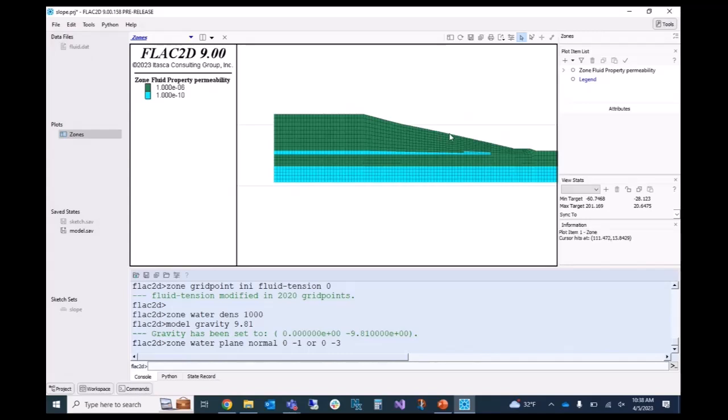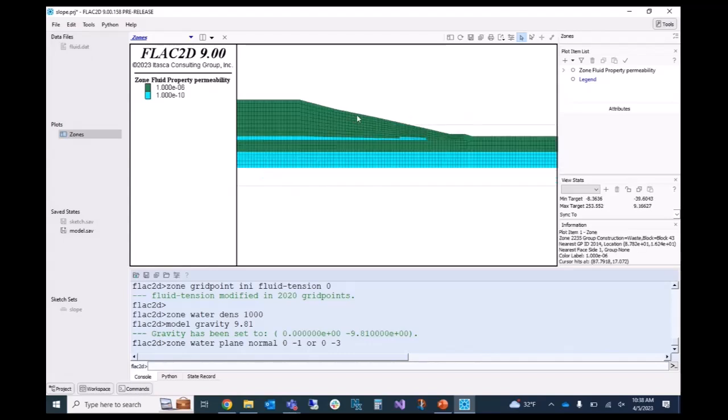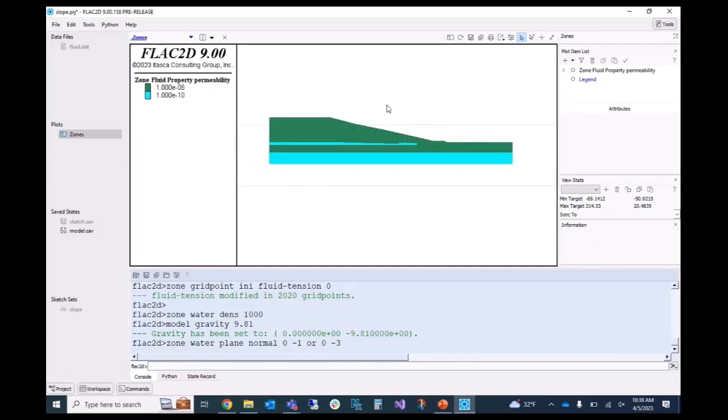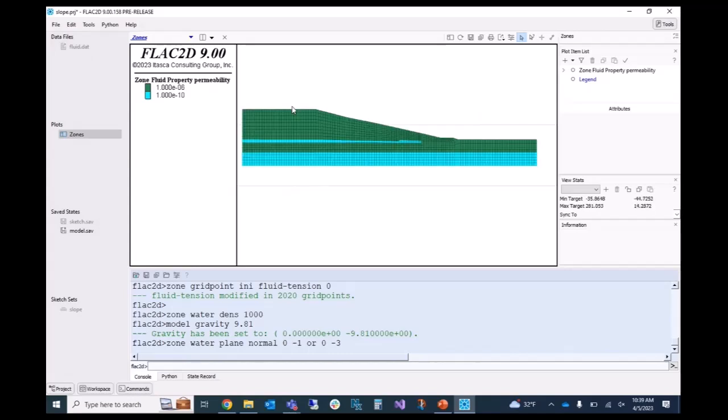And so by specifying a 0 pore pressure on the surface, it makes sense. You can actually simulate a situation with ponded water. You could specify a pore pressure that's not 0, and it will simulate ponded water here. In this case, we're assuming that there's not ponded water. So we want everything on the surface to have a pore pressure of 0. And we can identify that surface using the group name. Hopefully it worked when we assigned the group names automatically.